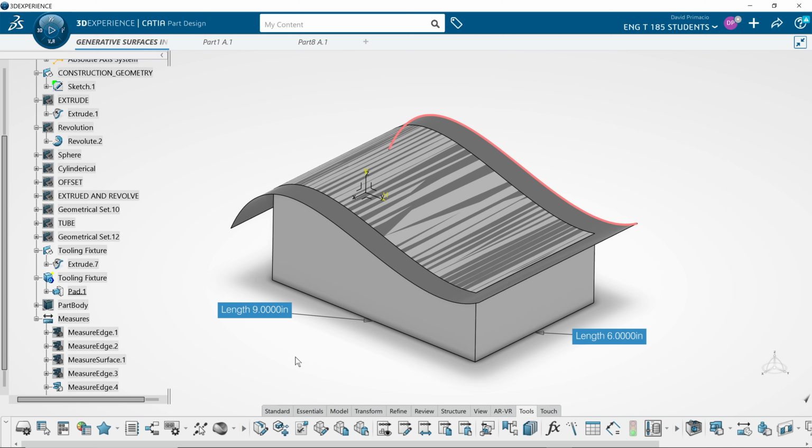I did a lot of the interior parts, the Nomex panels, sidewalls, ceiling panels, overhead storage bins, stuff like that, machine those types of things using a 5-axis machine. So in order to create the tool fixture, we have to create a solid and split it to that surface that represents the engineering part.